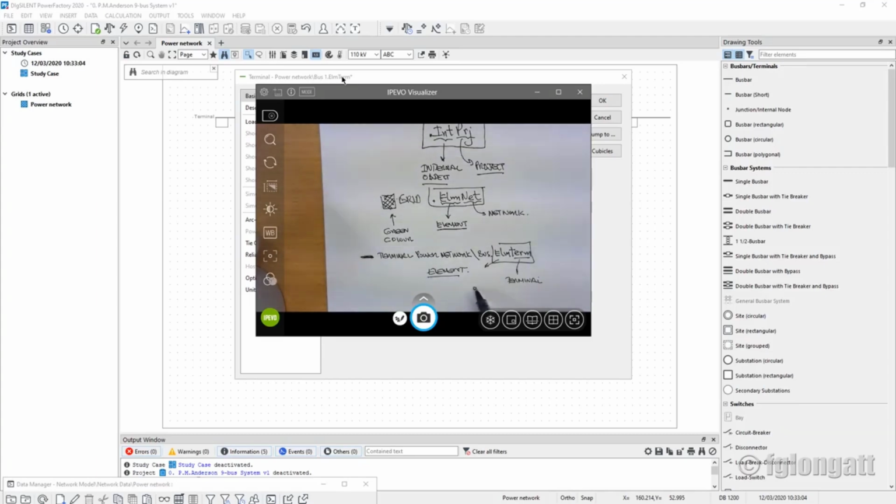Terminal is like any node in a power system. In a circuit, you can have many branches. Some of them bringing current into, feeding current into the nodes. Some branches putting current out. And that is the most basic representation for a bus bar inside PowerFactory. This is the ElmTerm terminal. Okay, this is an element, and the name is terminal. Okay, good.